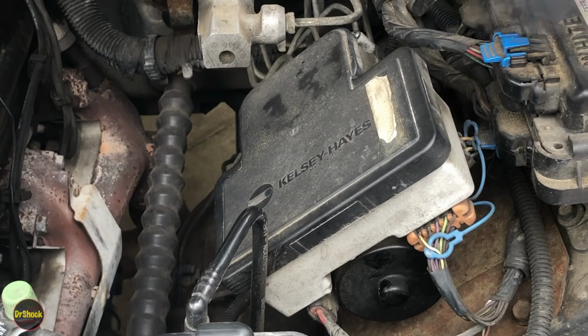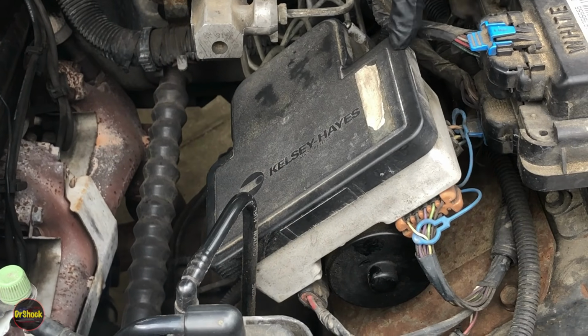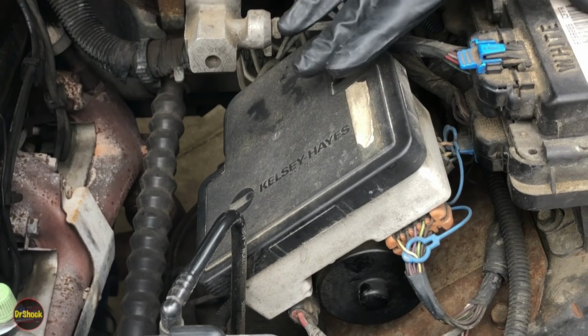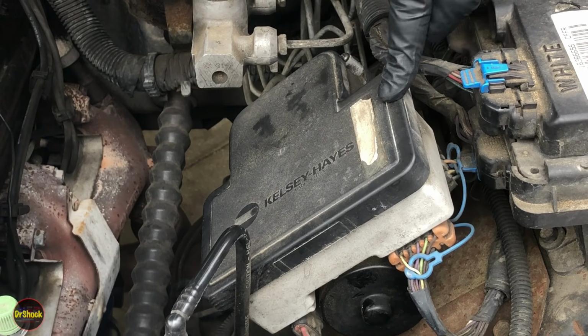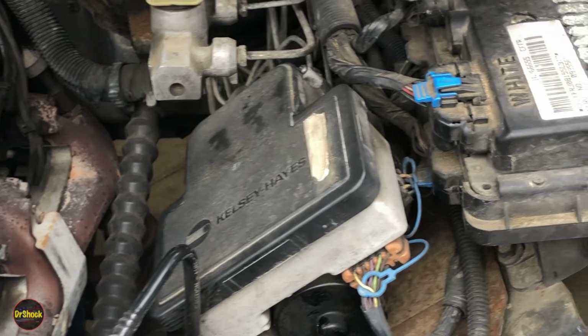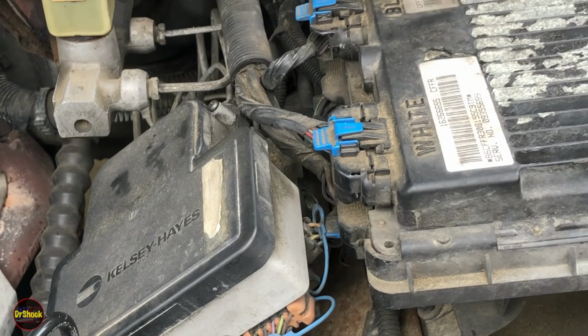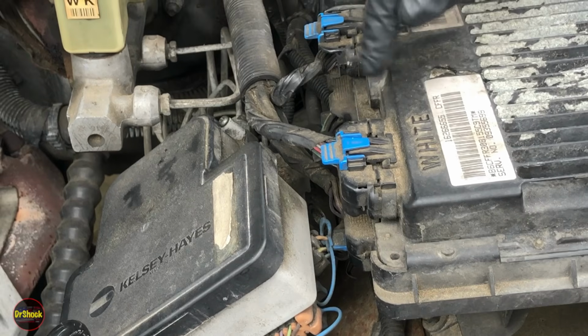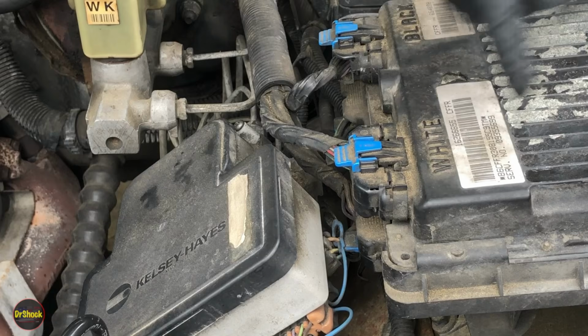But one more thing I want to show you before we diagnose the problem is just about familiarizing yourself with the layout. So this is a gasoline-powered engine that this is in, and when you have a gasoline engine, this EHBU is going to be right next to what's called a VCM, or a vehicle control module. Gasoline engines will have this mounted here. Let me show you a quick clip of a diesel truck that doesn't have this, so you can see the difference.